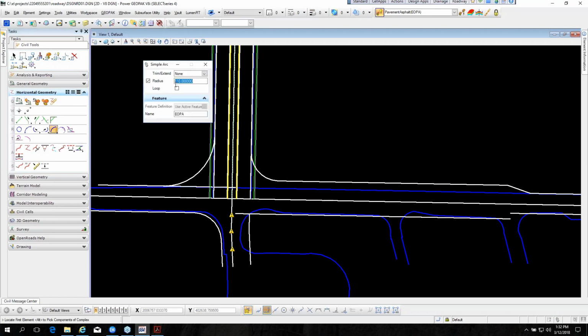That's going to be set to 60. And on this one, we can kind of go through and do those. So I'm going to set this to back. You guys can experiment with that, either back or ahead or both. We know what both is going to do, so we'll just kind of tab through that. So I'm going to go ahead and pick this line as the first one, and then this is my second. Place it, and then it says trim back. So it just trimmed this back line. It didn't trim this one. So if we do ahead, it would leave this line and then trim it back here.